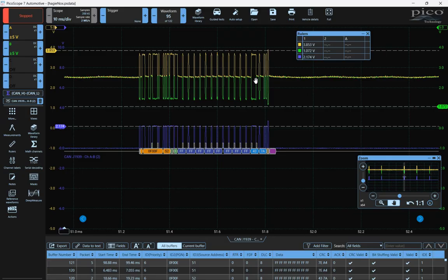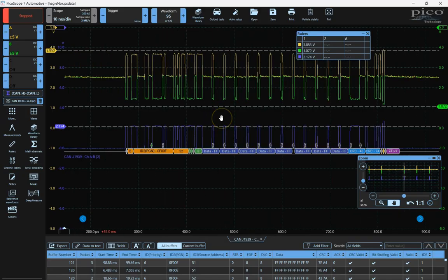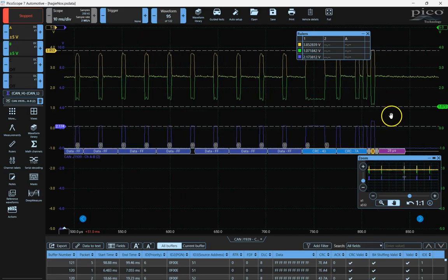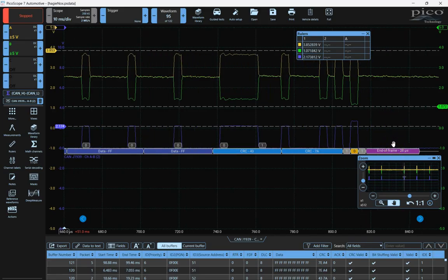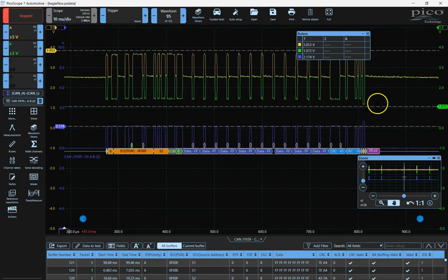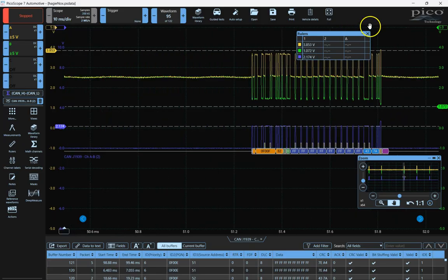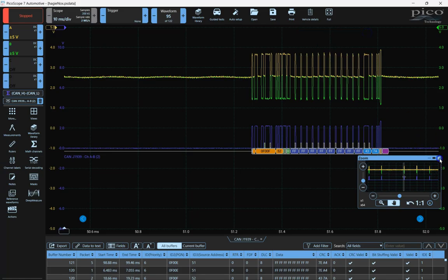You can see this message is a little clearer or a little plainer, but for the decoding piece of CAN and how robust it is, it doesn't matter. It's fine. That variation in voltage, that ripple, really doesn't affect us. So there's our acknowledge bit. We can look at it and see we have 28 microseconds of end of frame data, so we know this is a 250K CAN bus. If I measured the width of this, we would find that the acknowledge bit is 4 microseconds in width. Again, go ahead and get rid of my rulers, and we can take our zoom off.